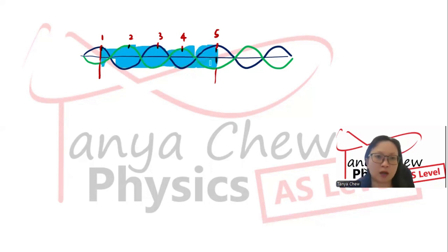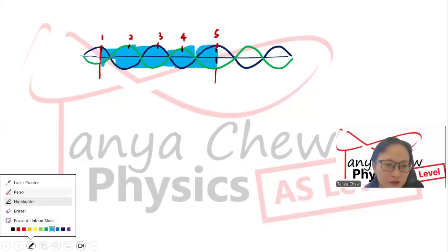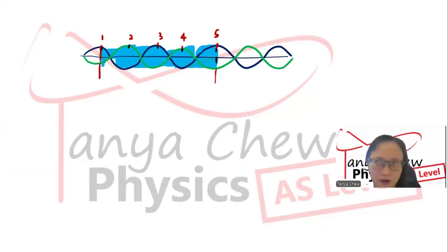Bear in mind, one loop represents 1 over 2 lambda. This is 1 quarter of the loop, so this is 1 over 4 lambda. This is 1 over 2 lambda, 1 over 2 lambda, 1 over 2 lambda, and 1 over 4 lambda. Add them all together. That will give you 2 meters.